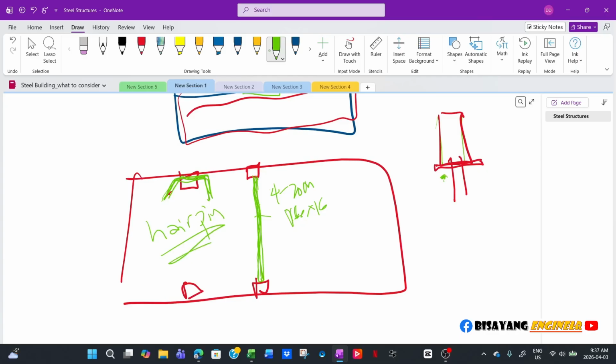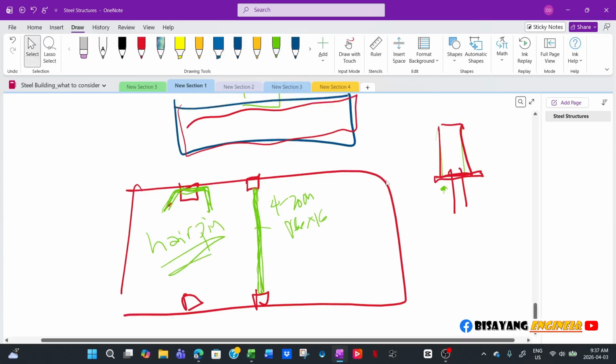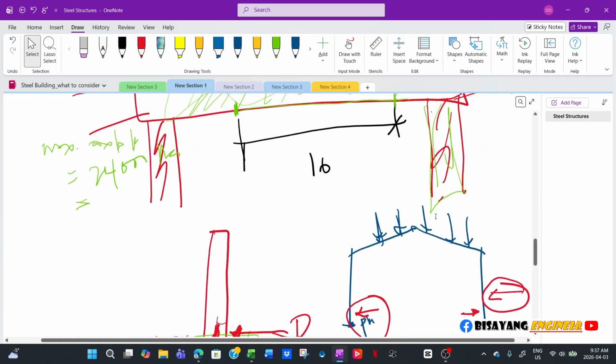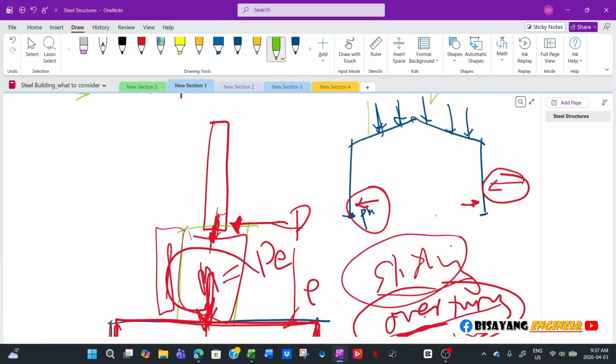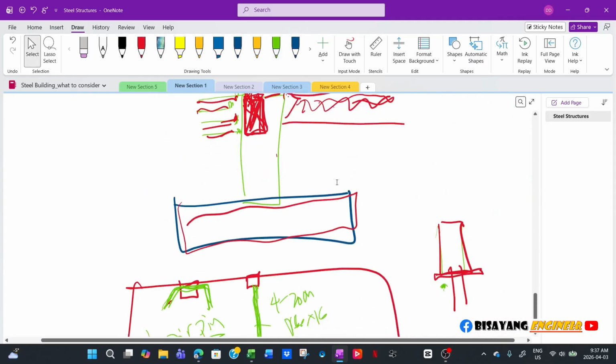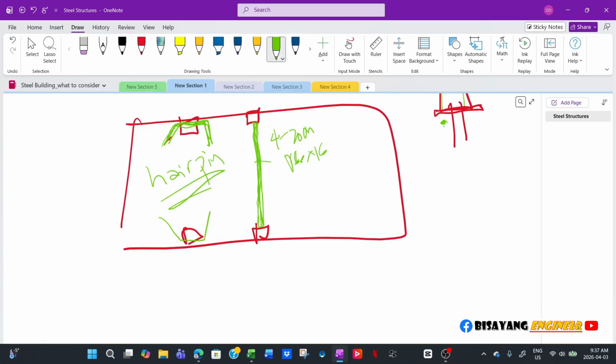So it will resist the lateral load, because like I said, the gravity loads will tend to result in kicking of your structure. So basically, if we have a hairpin tying these two together, so you have a hairpin here as well, and then you utilize this slab to resist all the tension, right? Because you have a slab, and it is reinforced, so you have some tensile capacity there.